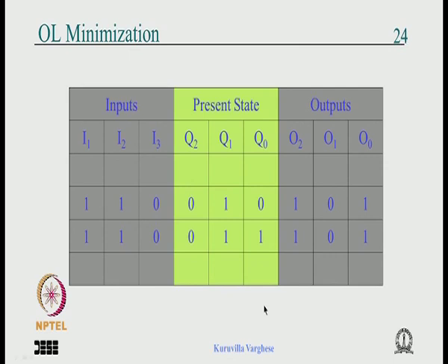Now the same heuristics can be applied to the output logic. You can straight away state the rule. Take the Moore kind of output: if two present states have the same output, then you just make them adjacent, like Si and Sj producing the same output, making them logically adjacent so that when we group, one literal gets knocked off. Similarly, if you have 4 states, you make all 4 logically adjacent, say 1 1 1 1, 0 1 1 0, 0 0 0 1, so that 2 literals get knocked off the min term.